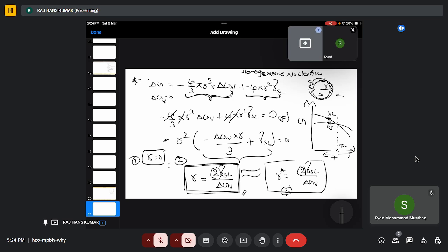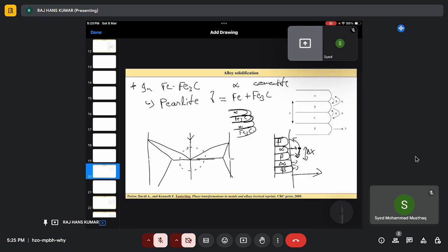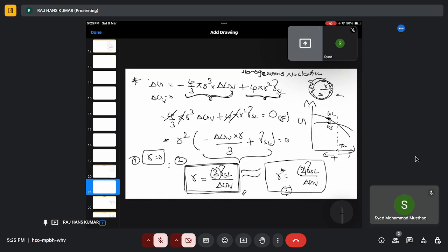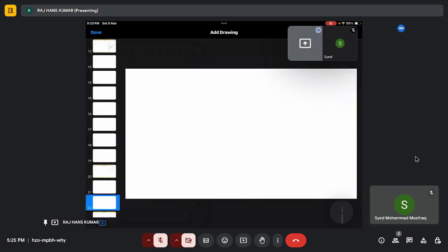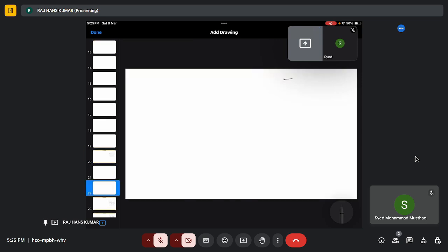Now, again, coming on to the new one, these guys. Let's say the interlaminar spacing between two, or the thickness of alpha plus beta, will be equal to lambda. Okay? Now, we can have an ideal case where lambda equals infinity. That means we are dealing with total volume.